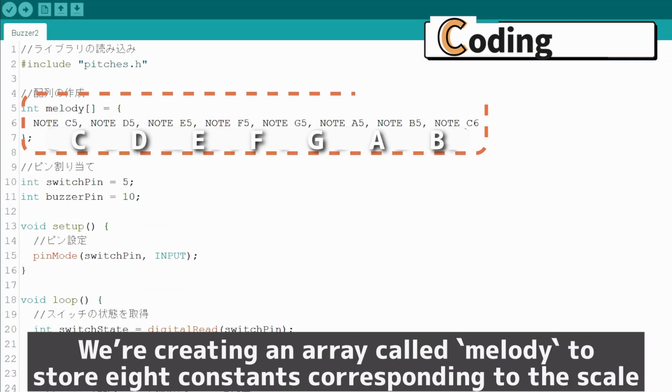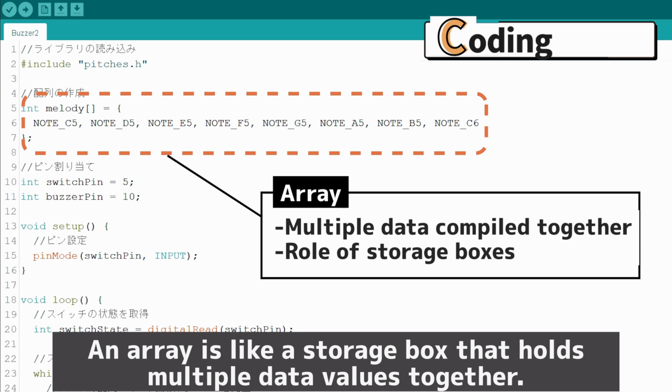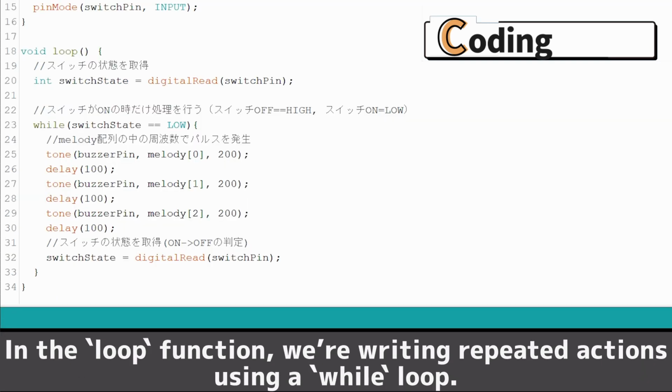We're creating an array called melody to store 8 constants corresponding to the scale do, re, mi, fa, sol, la, ti, do. An array is like a storage box that holds multiple data values together. You could write this code without using an array, but arrays help keep the code cleaner and more efficient by reducing redundancy. In the loop function, we're writing repeated actions using a while loop.